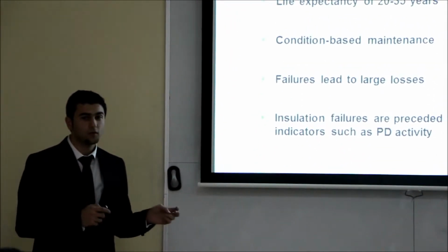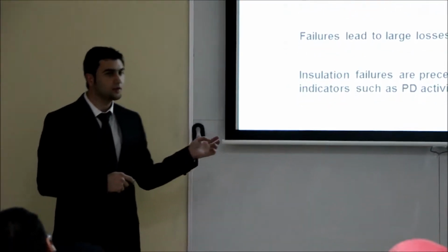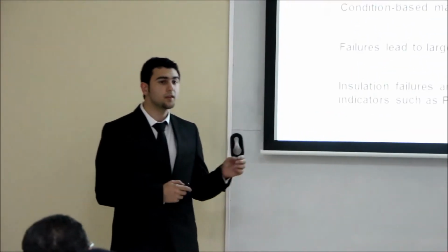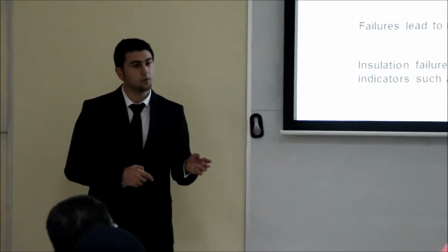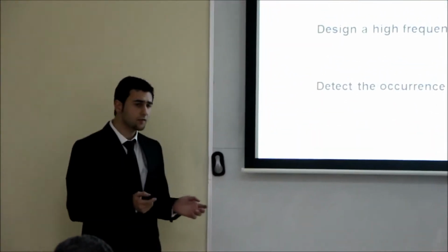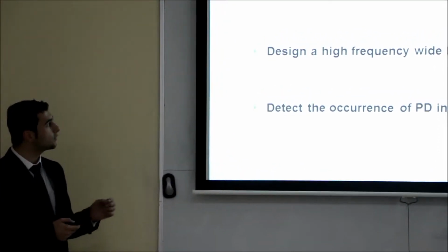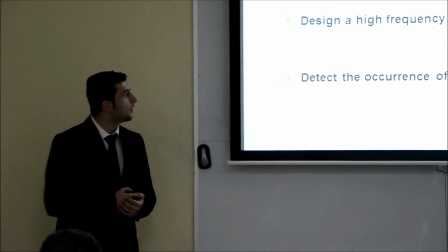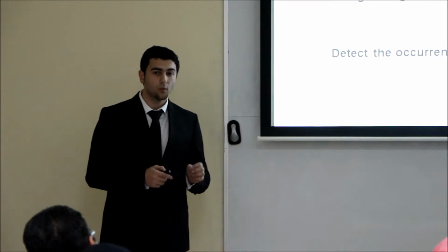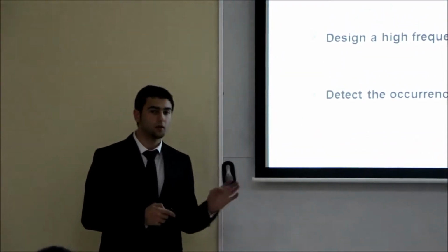To determine the level of the degraded insulation, some factors need to be monitored, such as the partial discharge. The detected level of a partial discharge can determine whether the transformer needs to be replaced or not. Our aim in this project is to investigate the high-frequency components of the partial discharge signal within an oil-insulated power transformer. To be able to investigate the high-frequency components, we need to design a high-frequency wideband antenna that is compact and capable of detecting the partial discharge signal with high accuracy.